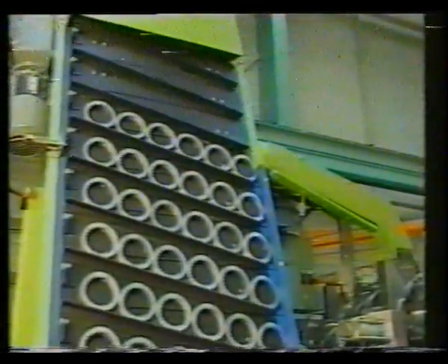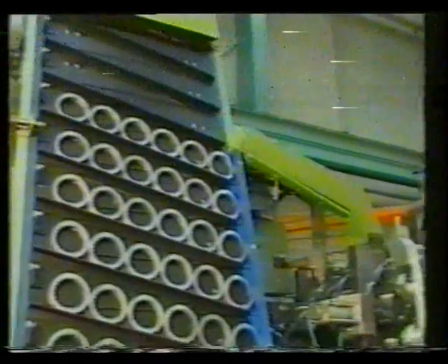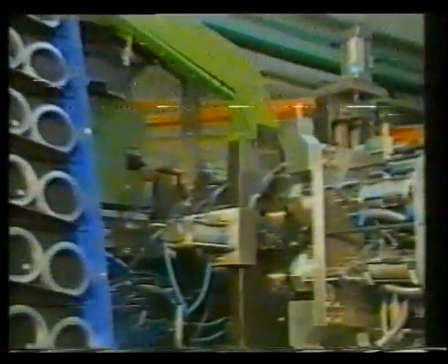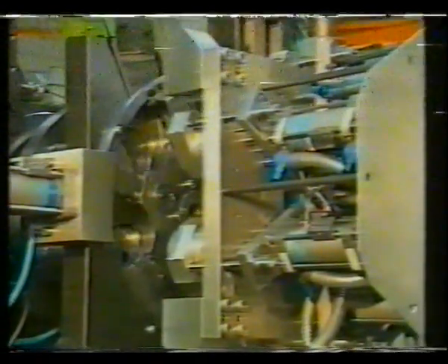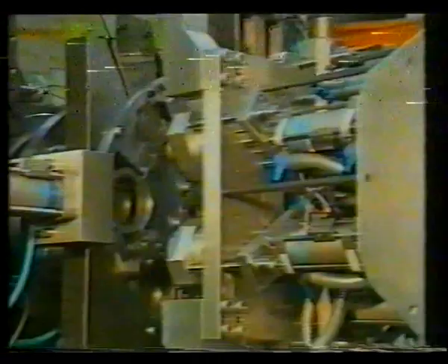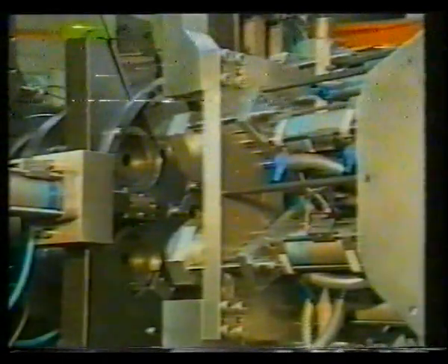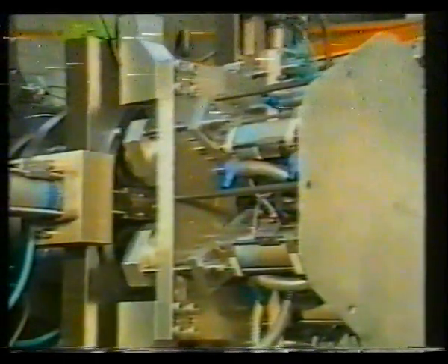The inserts required here for each cycle comprise 6 lamination stacks and 6 centrally arranged bearing bushes. This is how the inserts are picked up from the singling station by the loading unit fitted to the front of the machine and transferred to the die.